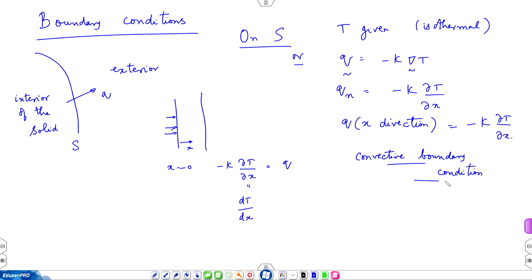That is a very hard problem to solve. So, the engineering approach is to employ handbooks. If your main interest is only in the solid medium, then the entire effect of fluid motion can be encapsulated through a convective heat transfer coefficient, parameter h, which specifies heat flux.